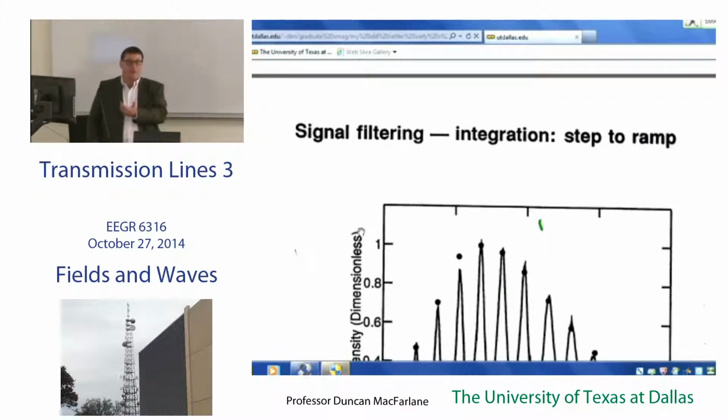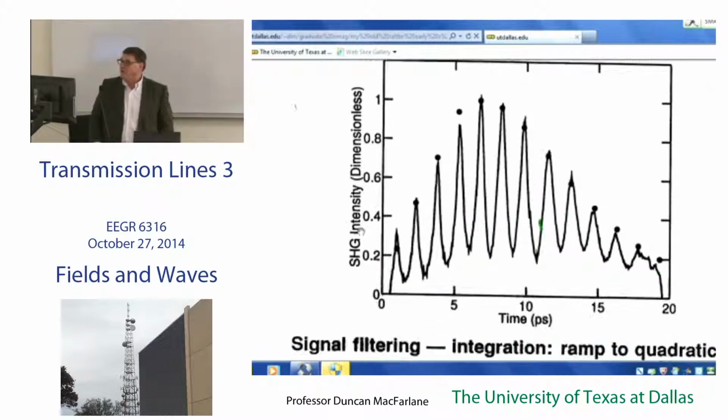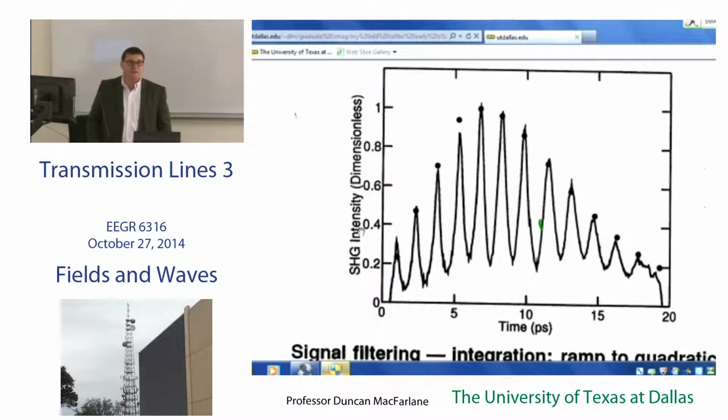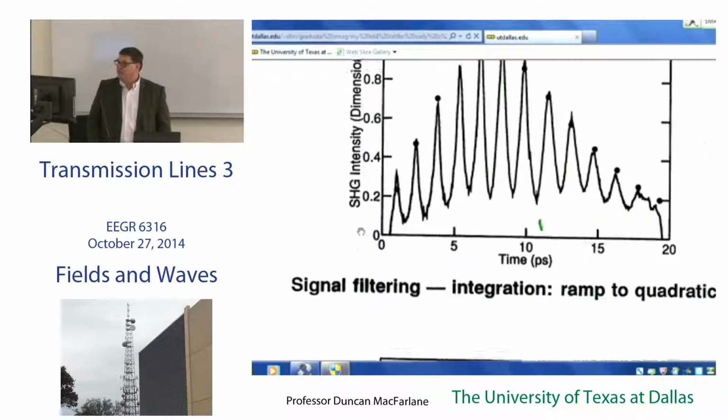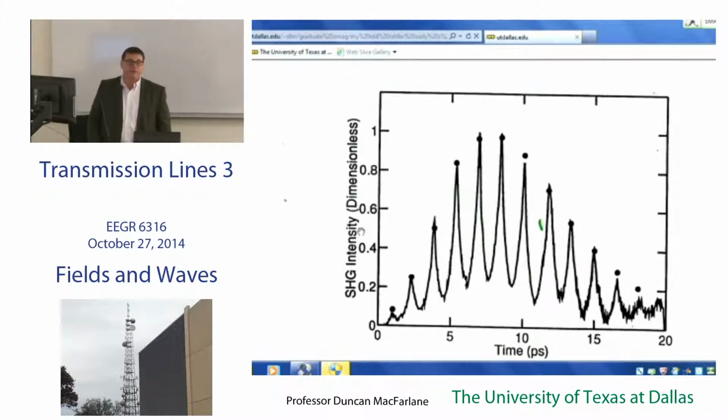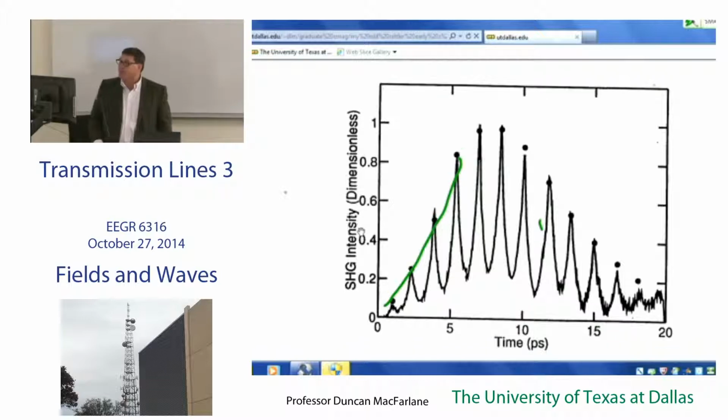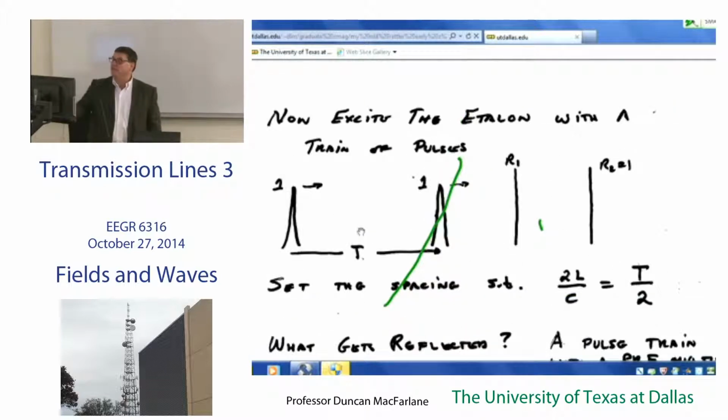If we sent this back into the same filter, we would take one pulse, go into a step, we would come up with a step function, and then we'd come up again with a ramp. And so we're doing simple integration. And then again, if we did the same thing back into the same filter, this is getting a little bit beyond our control, but we begin to get a quadratic rise in that. And again, all this processing is done at a tremendously fast rate.